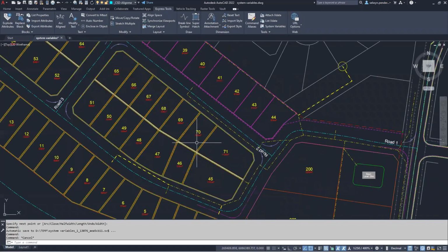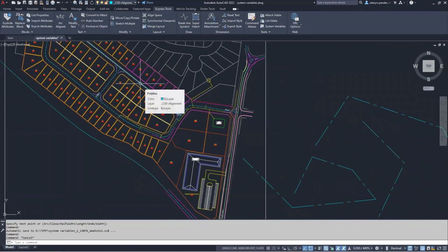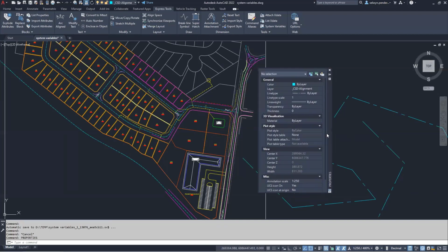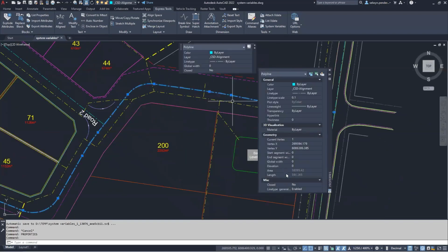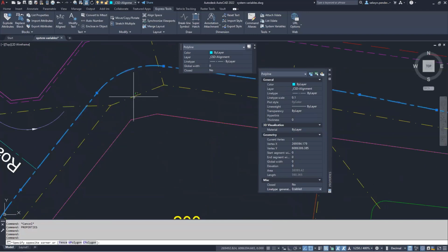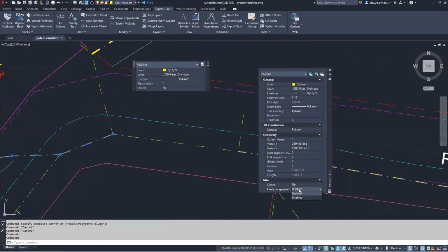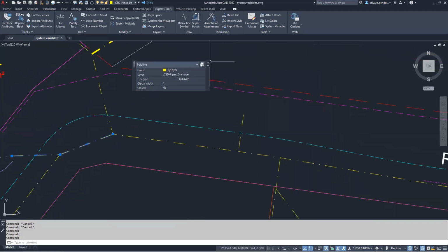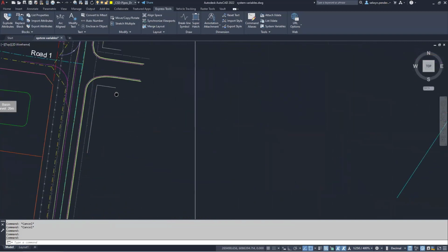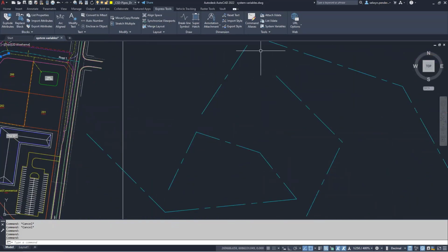All polylines in the drawing at the moment won't change. However, you can change the properties of them in the normal manner. Just bring up properties, and there'll be a line type generation option in there, and you'll be able to modify those ones. So if I just bring up properties for a polyline, I'll just come into this one here, and we'll see that we have line type generation enabled. If I turn it off, it goes back to the end-to-end settings. Actually, this one here might be a better one to look at. So if we turn that one off, we have the full segment coming through in here. So I'll just turn that one back on. So you can access the line type generation in there, but if it's set as a system variable, any polyline that you draw will be using that setting.